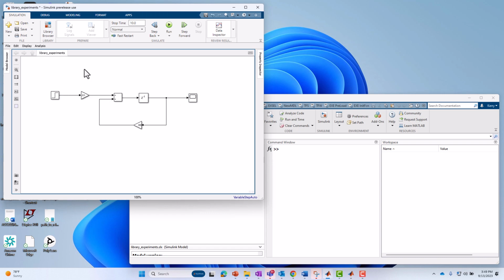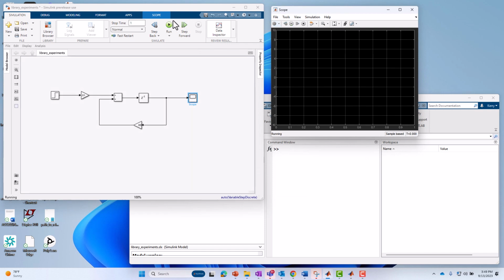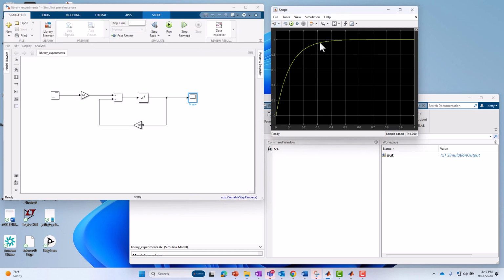And this is, again, we haven't created any library yet. We're just creating something which will become a library component. So let's run this for a second. I'll pull the scope up so we can see it run over here. I'll hit play on the scope. Could hit play over here, and you can see it ramps up instead of having a perfect, infinitely fast rise time. It's got some roll up, rise time associated with it. All right, so that's our classic simple leaky integrator, and you could compute the time constants from these coefficients